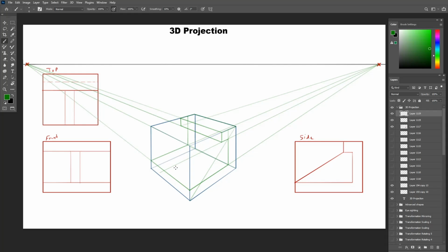Now that we have the surrounding shape, it's time to add the slope in the middle. To get the slope in the middle, I find the center for the bottom platform and then divide 1/2 twice till we get the quarter of the distance on both sides of the center line. From there I can project these lines back and up toward the ledge and pinpoint the location of the slope there as well.